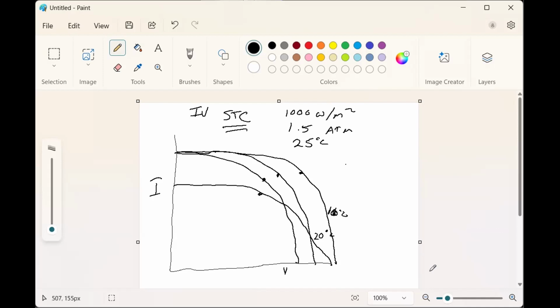And fortunately, there's a device called the MPPT, the maximum power point tracking device, and that's located in the first piece of electronics that is connected to that panel. And that is going to just automatically adjust on a millisecond by millisecond basis where that panel is going to generate. And it's going to be jumping all over the place as temperatures change and as irradiance changes.